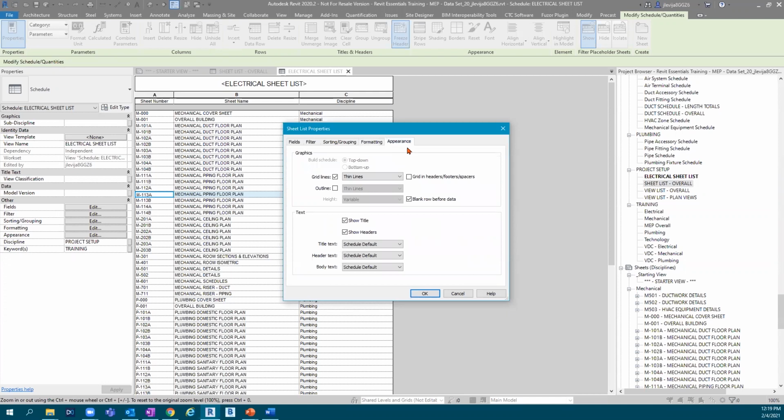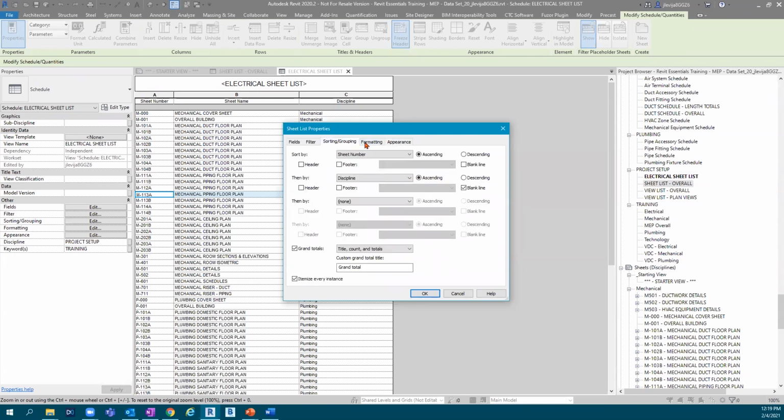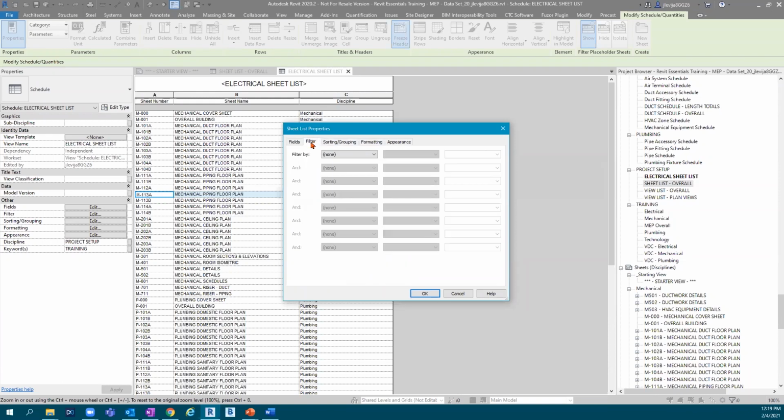And then finally, for appearances, this is a topic of discussion when it comes to appearances. So here in Revit, we can customize based upon the actual schedule like this, and we can keep all our controls right in the individual schedule. Otherwise, there are opportunities for view templates, and that view template can adjust your appearances. So you do get some of that flexibility, right? So now we're going to stick with kind of what we have out here.